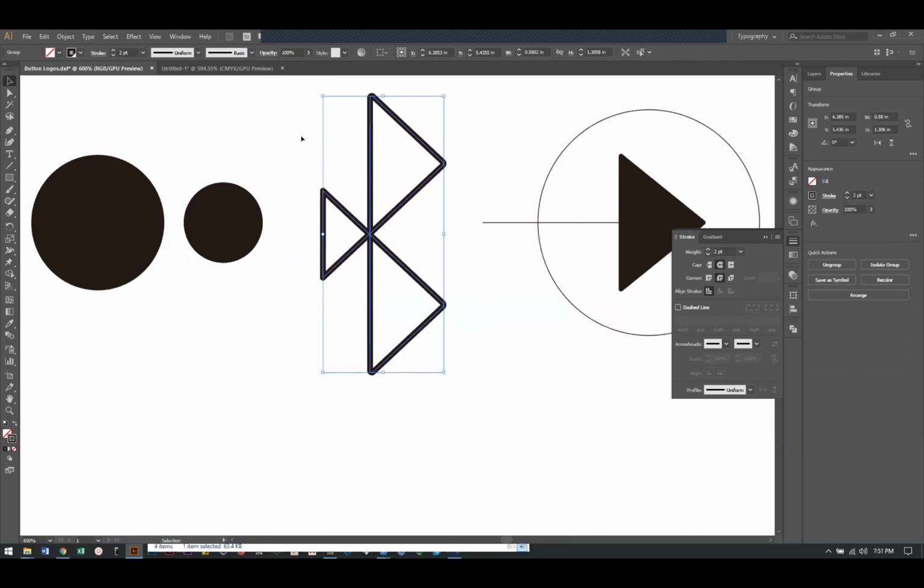So join is like join in Rhino, where it actually creates a single piece of geometry out of multiple pieces of geometry. As opposed to group, which takes multiple pieces of geometry and allows you to grab onto them and use them as if they were one piece. So it's different.